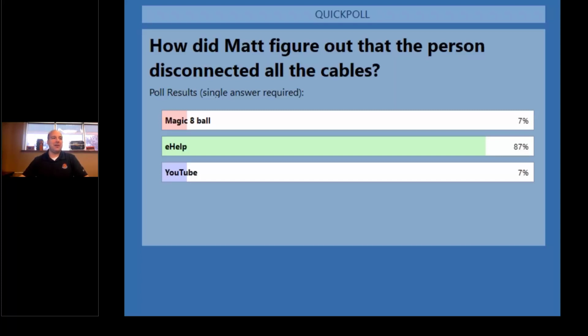So within the CAN function, it actually has a specific piece that shows you CAN harness fault, harness A, harness B, harness C, harness D. And I could tell that that happened because I could see that they went and just pulled it off and pulled it back on because it said harness A, harness B, harness C, harness D very, very quickly within just seconds of each other. And the person was able to get the engine to run again, but did they really troubleshoot it?